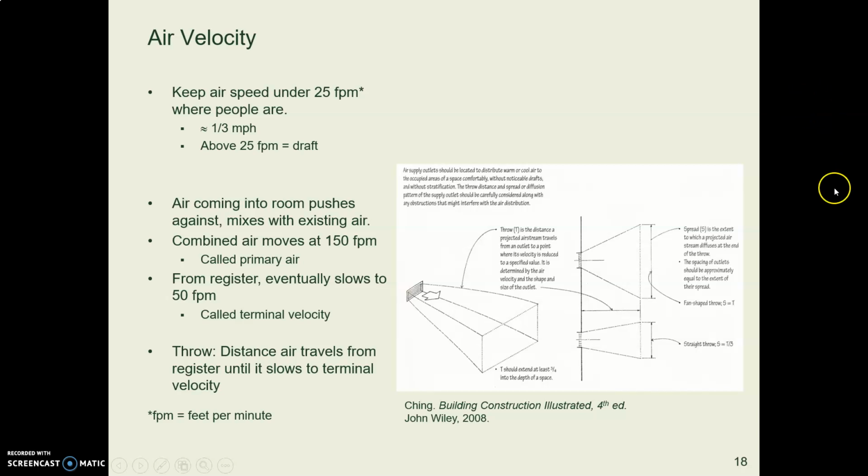A furnace requires smaller duct sizes, smaller diameter or cross-section. A heat pump requires big ductwork. So when you put in a heat pump, in many cases, you need to replace the ductwork. And in old houses where they have not done that, when they put in the heat pump with the blower, the thing starts whistling like crazy. So we want to watch out for that.